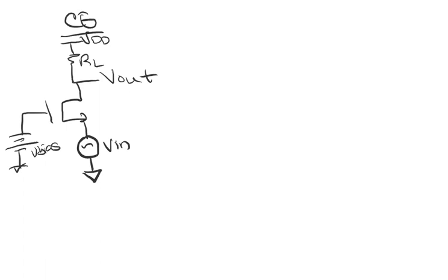So now I have to do what? First, I have to bias the device such that it's in saturation. So the first thing you do is bias the device for saturation or check that the device is in saturation. Remember, amplifier devices, MOSFETs, must be in saturation to work properly and to be able to do a small signal analysis. So now I'm going to draw the small signal model of just my MOSFET at low frequency.